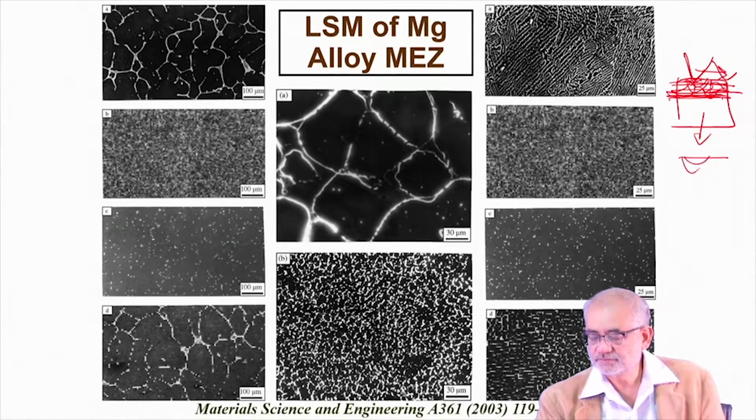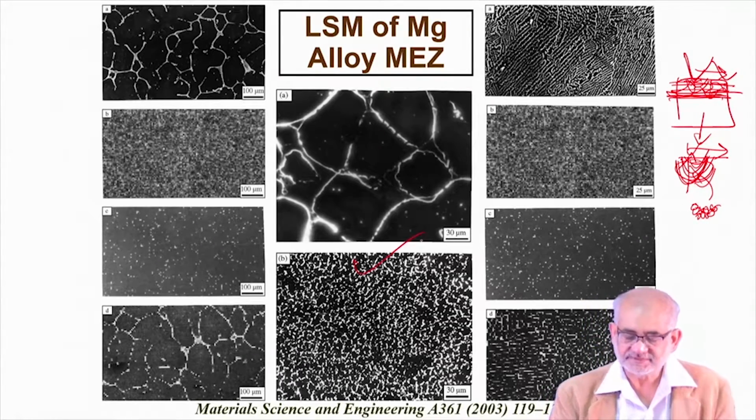This is how the molten zone penetrated into the depth, and this is the final solid liquid interface position. By the time the beam moves away, the solid liquid interface will recede to the surface, and when it recedes, this region becomes solidified, and this solidified microstructure will be extremely fine. The grain size will be extremely fine, and this is exactly the effect we are seeing here.